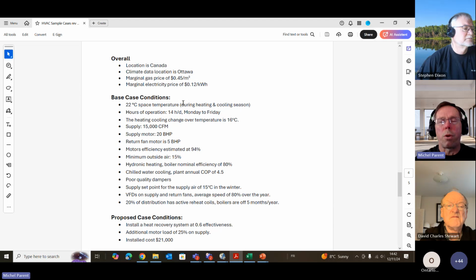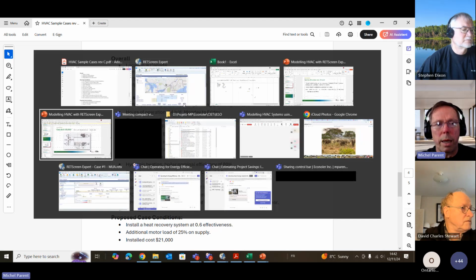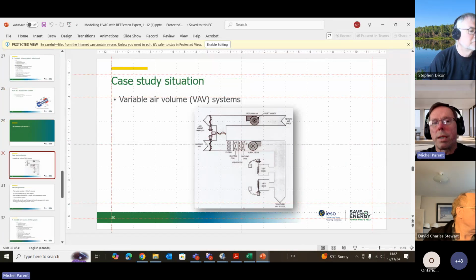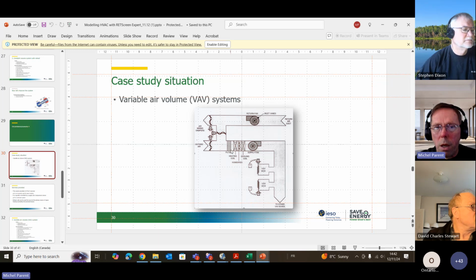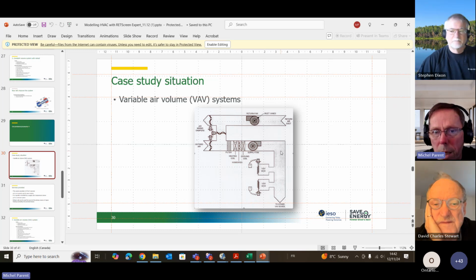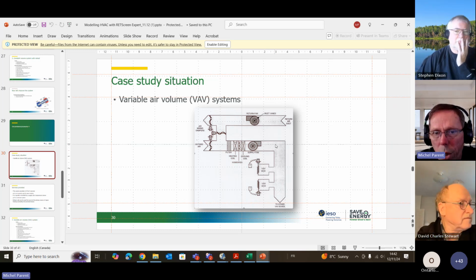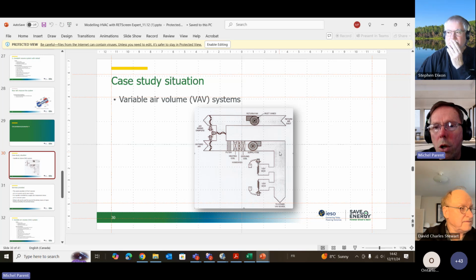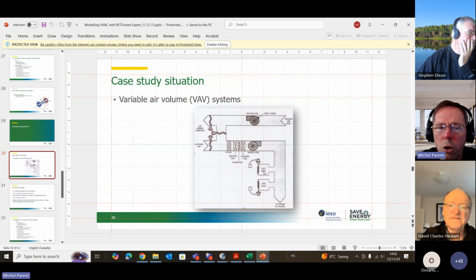And remember, a VAV system, if I go to the slide that we had before, is very similar to our reheat system. So it's a recirc system with our economizer, our mixed air temperatures right here. But instead of reheat box, we have VAV box. But it's a cold deck system because the heating and cooling coils are controlled by a duct temperature sensor, which 95% of the time will be cold deck. So it's supplying below or at most at room temperature.